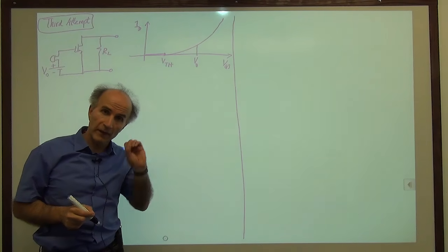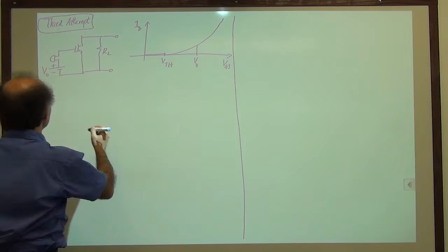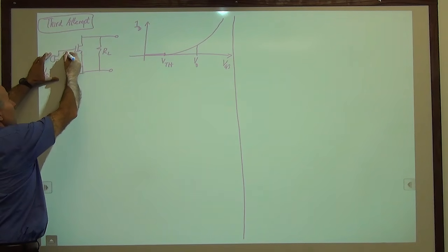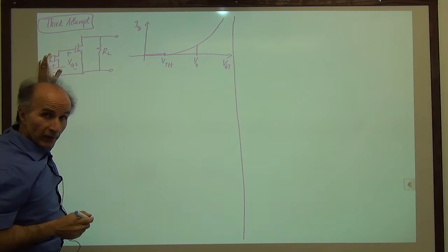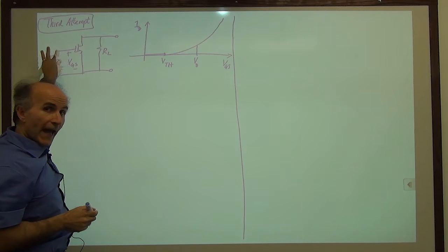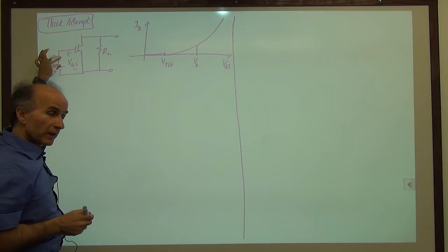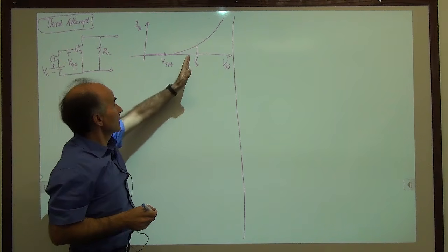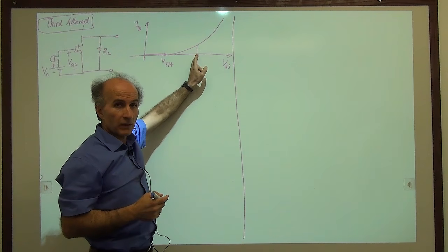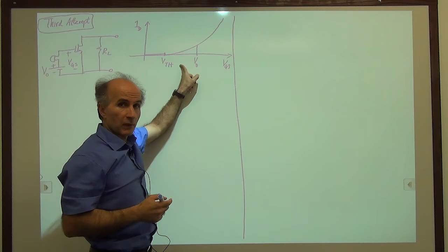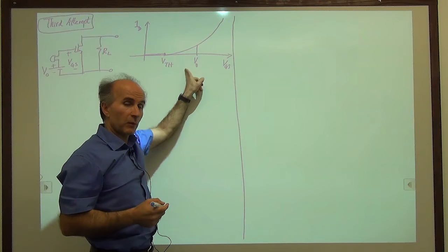So now the microphone signal comes in. It comes in, and this VGS is now modulated, so to speak, right? So in the absence of a microphone signal, when this difference is 0, VGS is equal to V0. When the signal comes in, VGS goes up a little and goes down a little. Let's say by 5 millivolts this way and 5 millivolts this way.